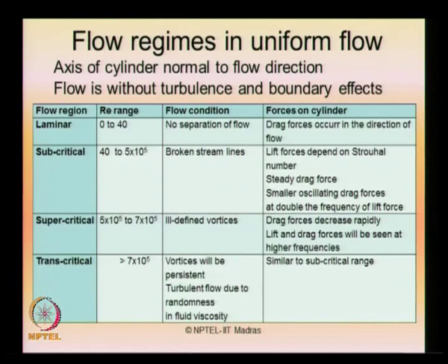You can see this, that is why we can say there are broken streamlines, whereas when you move to the supercritical region the drag force decreases very rapidly and lift and drag forces seem to occur at higher frequencies. In the transcritical region the behavior is more or less similar to subcritical, that is why the validity of experiments people have conducted in subcritical is extrapolated to some extent to higher Reynolds numbers also, because the force on the cylinder seems to be similar to that of subcritical behavior.